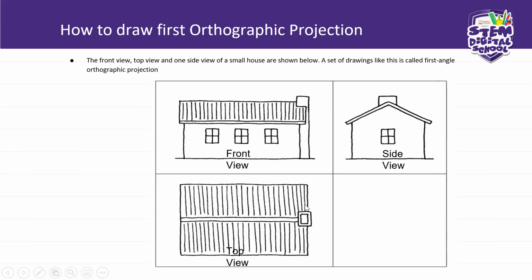So these are the views that we draw. We draw the top view and the front view, but the side view we project from the top view by aligning the lines. If you can check this line, although it's freehand, it's aligned. Even the top, it is aligned, although it's freehand. Okay, be mindful of that.